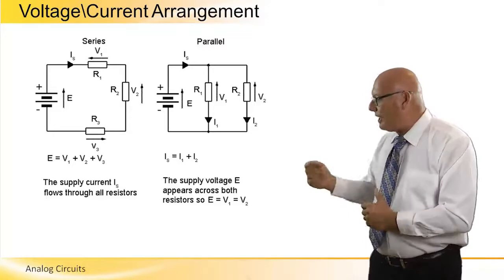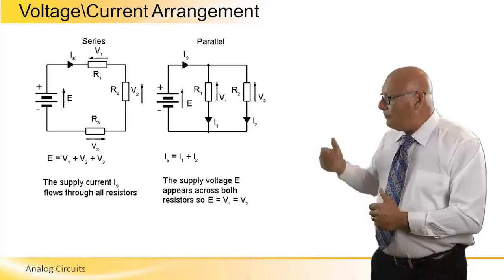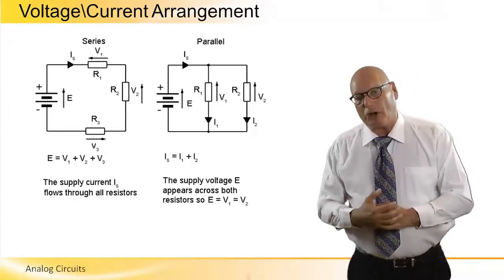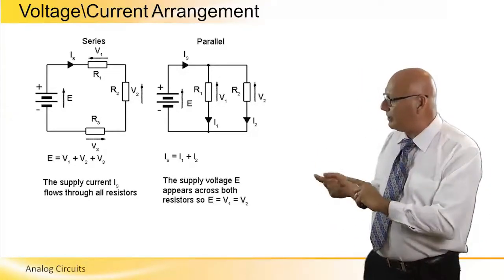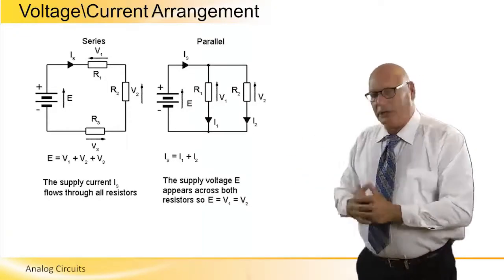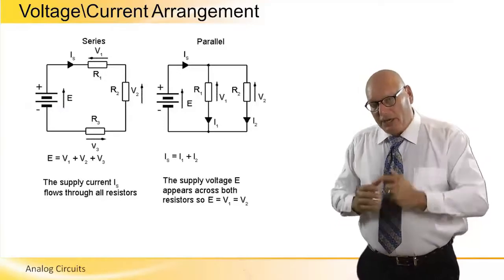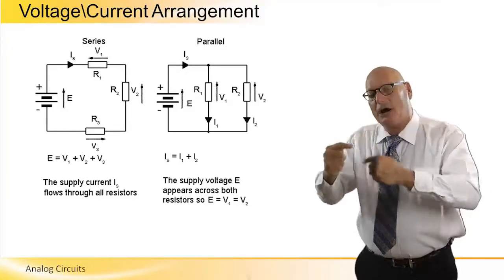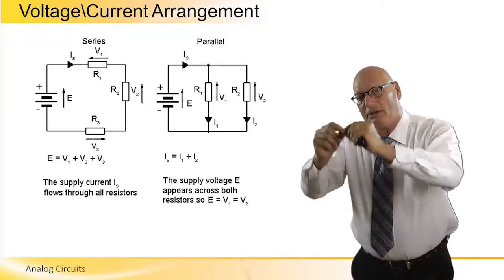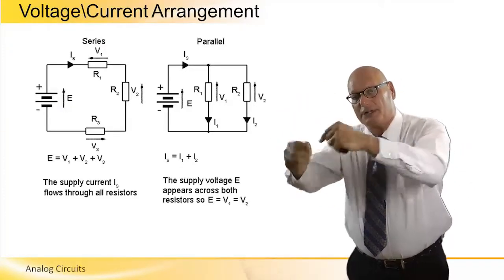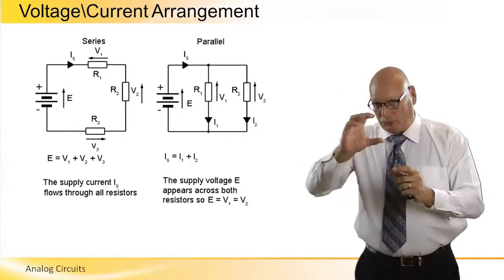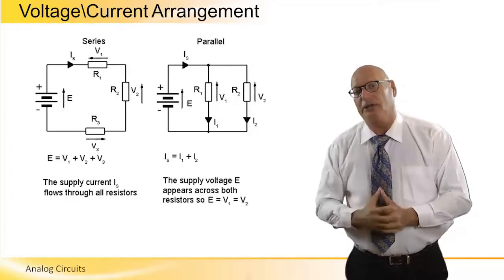And the plus on the right is connected to minus on the bottom of R2 and plus on the top of R2, which is connected to the right-hand side of R1. Negative, and the left-hand side of R1 will be positive, and these are exactly like cars of a train. Plus is connected to minus on one side, minus is connected to plus on the other side, and this is how we chain all these voltage drops together to come out with the voltage of the battery itself.